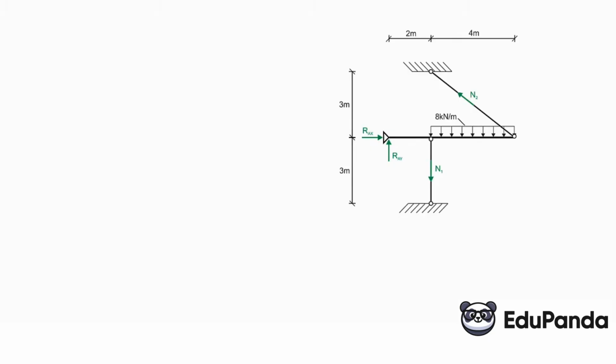In this task, we can use 3 static equilibrium equations since the sum of the projections on the x-axis and y-axis will give us some relationship. Because the forces are at an angle, we have them in both directions. And the sum of moments will give us some relationship. But we have 3 equations and 4 unknowns, which means the task is statically indeterminate. We need a geometric condition.